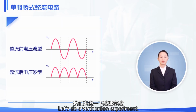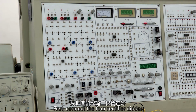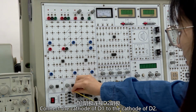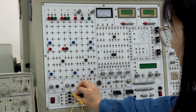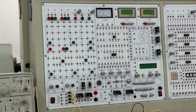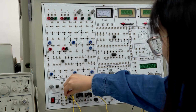Let's do a verification experiment. First, connect the 4 rectifier diodes. Connect the cathode of D1 to the cathode of D2. Connect the anode of D3 to the anode of D4.